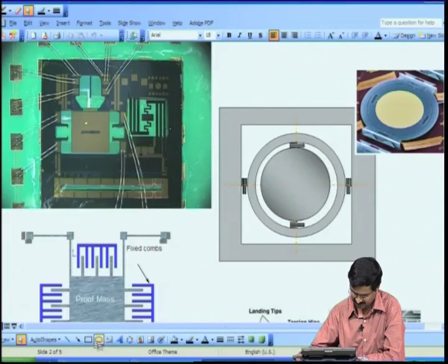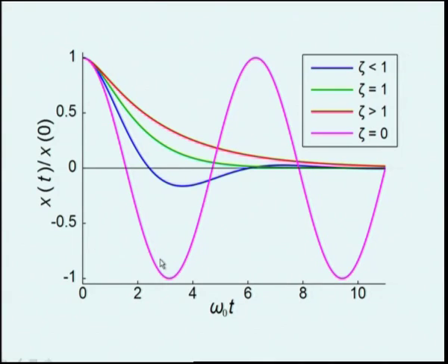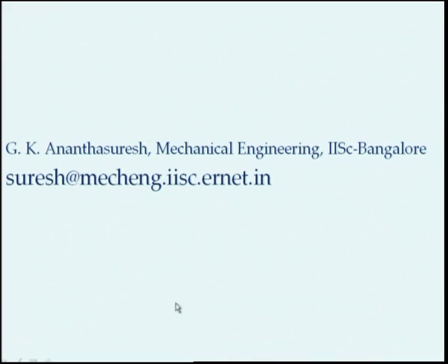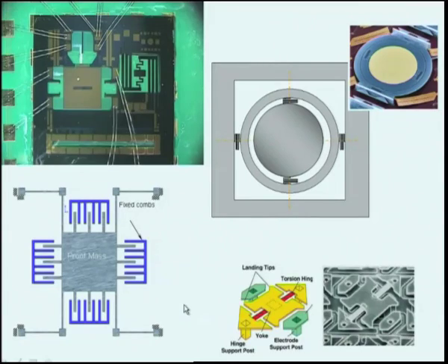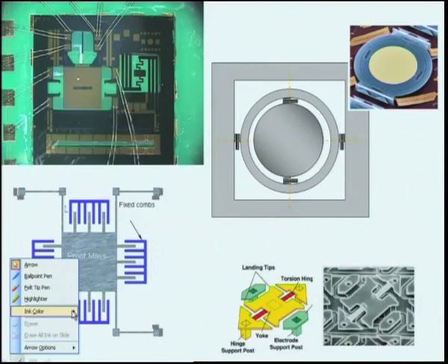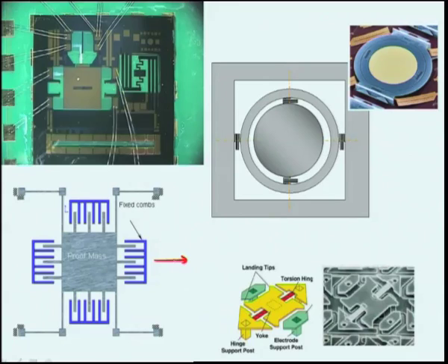So, if I take, let us say, this gyroscope, in fact it will have 2 degrees of freedom, meaning that it can move in the x direction or y direction. So, we have to go back. So, let me get a pen here. Okay. If this proof mass vibrates in this direction, or it vibrates in this direction, then we can reduce it to something like this.